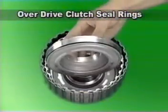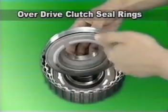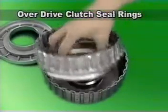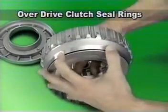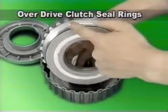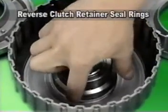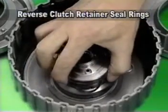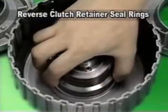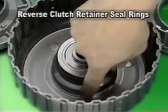Now the seal rings placed in the outer part of the overdrive clutch piston and reverse clutch piston. That is, the seal rings placed in the outer part of the overdrive clutch retainer are for the prevention of oil leakage when each clutch is in use. Between the 2 seal rings installed at the reverse clutch retainer, the upper ring prevents leakage in overdrive piston operation, and the lower ring prevents the leakage in reverse clutch piston operation.